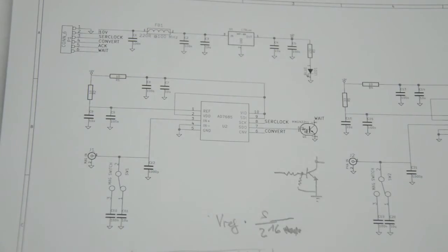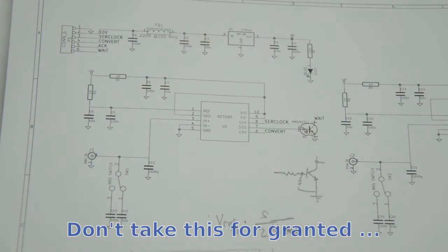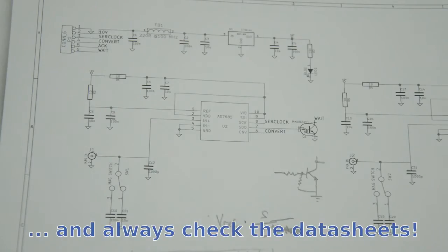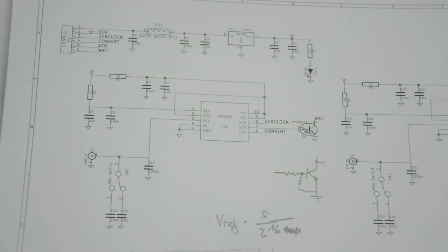Typically, this just means that the voltage is going to sit somewhere in that range, and it doesn't change too much. Of course, it changes with temperature, and the datasheet has a graph on how much this is going to change depending on ambient temperature. But it is far less than the 500 millivolts total range the output could swing between.